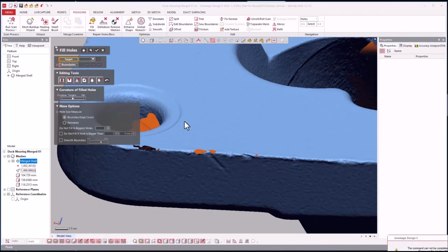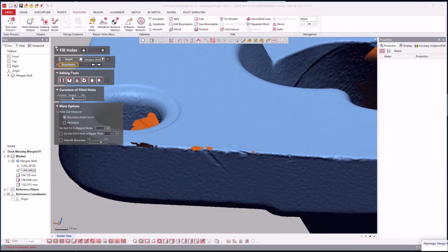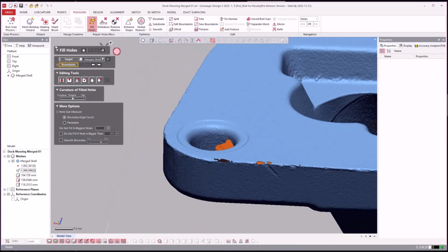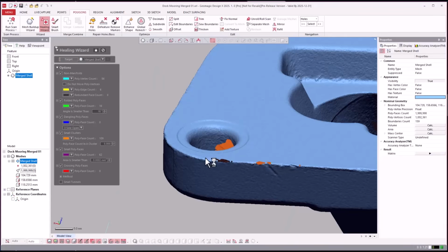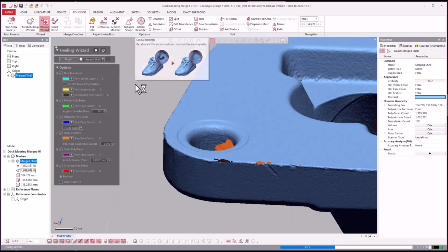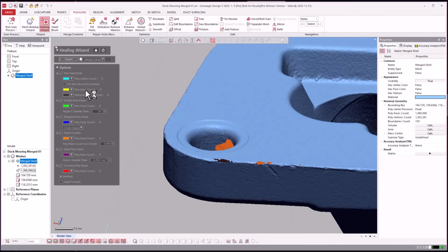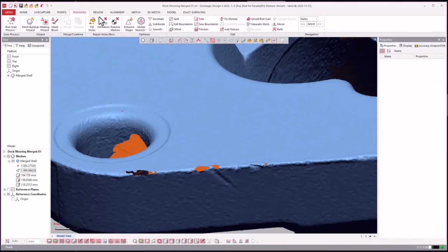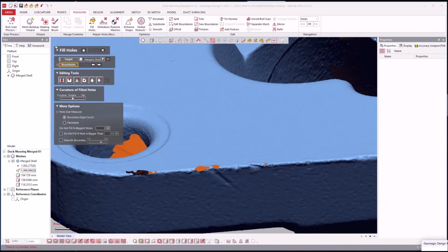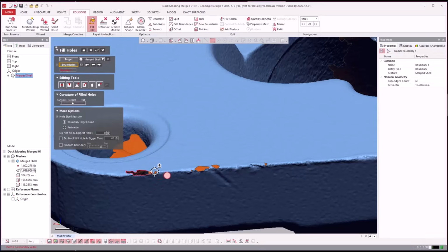So I did a one-off hole fill, and you'll see that that error is popping up, basically just telling me before you go fill stuff, you can run the healing wizard. So I'm just going to run the healing wizard, and it will go ahead and repair a lot of this stuff automatically for me. Actually, I could run that before my decimate, after my decimate. I actually intermittently run Healing Wizard throughout the process. And after I do hole filling, I usually run it as well.